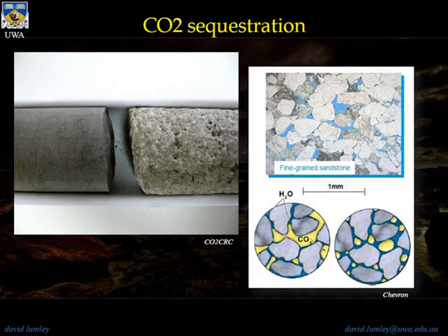And what's clear is that the dry samples are changing as a function of CO2. In other words, the CO2 has got in there, is chemically reacting with the rock and weakening it. And that's a huge amount. If you do some quick computations, that's 15-20% over just a few weeks of CO2 injection.